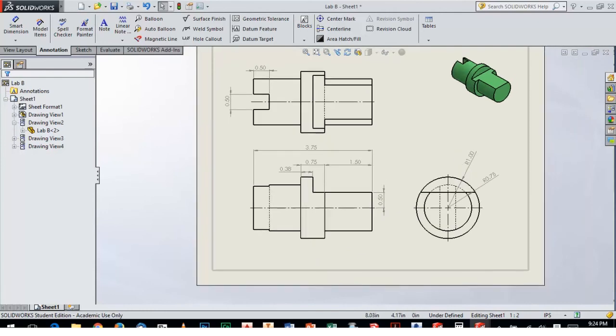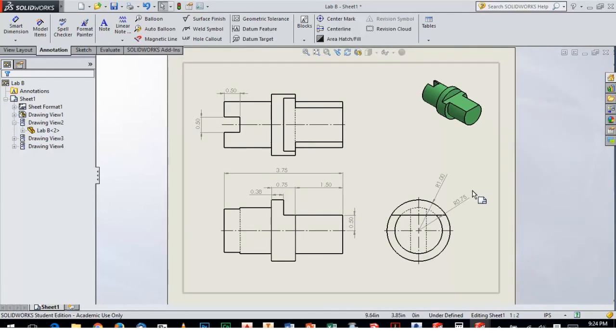So basically for that part you can go through and replicate the dimensions that are on the handout that I gave you, but make sure you don't repeat any dimensions and that you have all the dimensions you need on there. So that's basically a quick review drawing in Solidworks to give you some practice with some of these commands and look a little bit more at using global variables to dimension our parts and include design intent, and also a little bit more practice with creating a drawing page with views and dimensions and hidden lines and center lines.